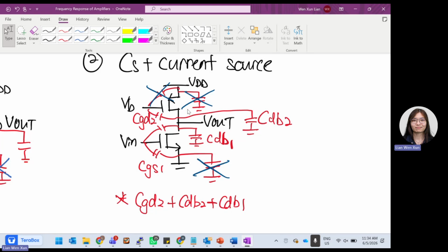First, we start from the top. In the small signal model, VDD is basically grounded. So here is ground, here is also ground. So this transistor can be cancelled out directly. And then on the left-hand side, this transistor at the top left, VB is a bias voltage, it is grounded. VDD is biased, so it's grounded. So this transistor also cancels out already. At the bottom also ground and ground, so this also cancels out. So I got 3 capacitors cancelled out. The circuit looks slightly easier already. And we can still combine a few things some more.